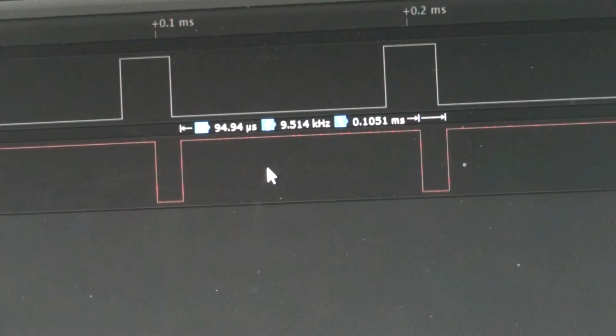I don't know how long it will take for this to download into YouTube, so you can have a look at it, and I'm not sure if that will happen tonight, but I can send you the software that we've got so far, and it's something that you can experiment with. But you've got to look at these things, think about that serial communication, because that's going to be a problem. You may have to change to a hardware UART. I'm sure you're only using that for diagnostics, and possibly you won't need it in the final version, but it just gives you an idea, and it shows you actually what's happening in the software here. I hope that helps.